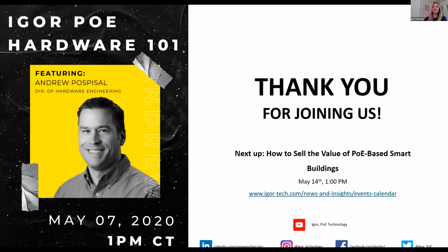Great. David's asking, based on some of your answers earlier, if you can mix Rev 5 and Rev 6 nodes on a daisy chain and connect it to a 90 watt port switch. Will the Rev 5 nodes get damaged? No, it would probably be a rare scenario. You would have to use a Rev 6 linear network node in order to get that 90 watts plus from the port. First of all, if you plug a Rev 5 network node into one of those switches, it's only going to grant you 60 watts.